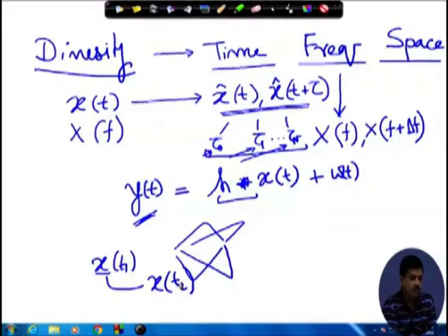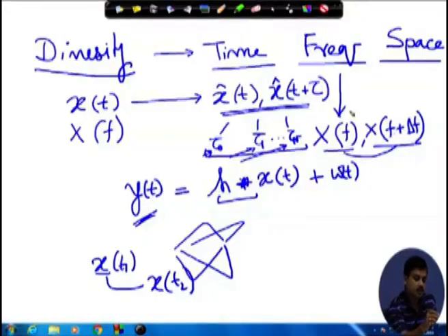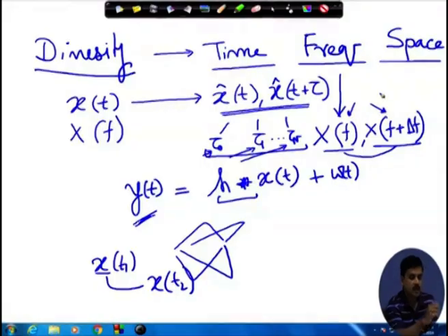If I look at the frequency domain, again if there is a spread in the Doppler frequency, I would receive the signal at f and I would again receive the signal at f plus delta f. And if there is frequency selectivity, then also the copy of the signal I receive at f and the copy of the signal I receive at f plus delta f are again uncorrelated.